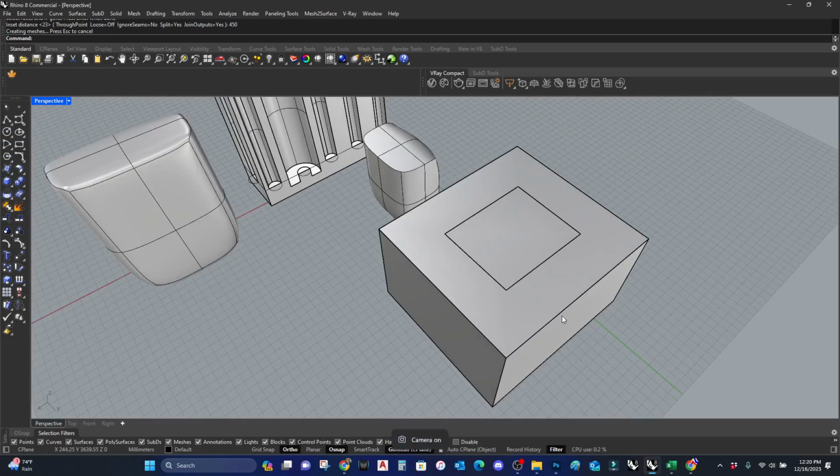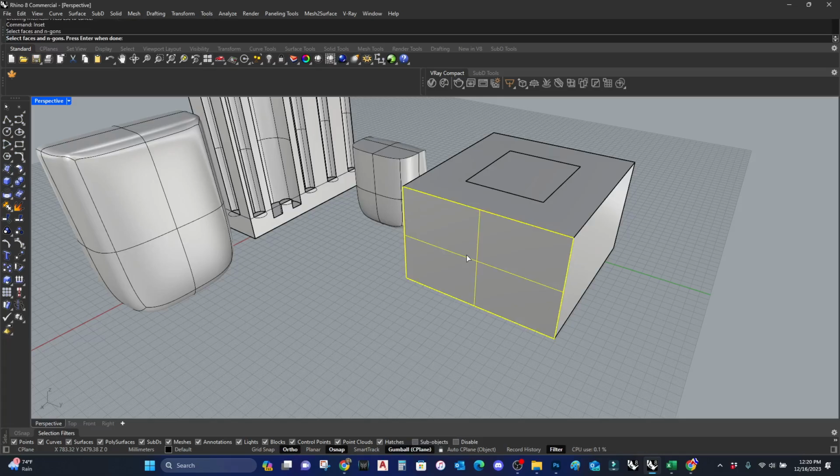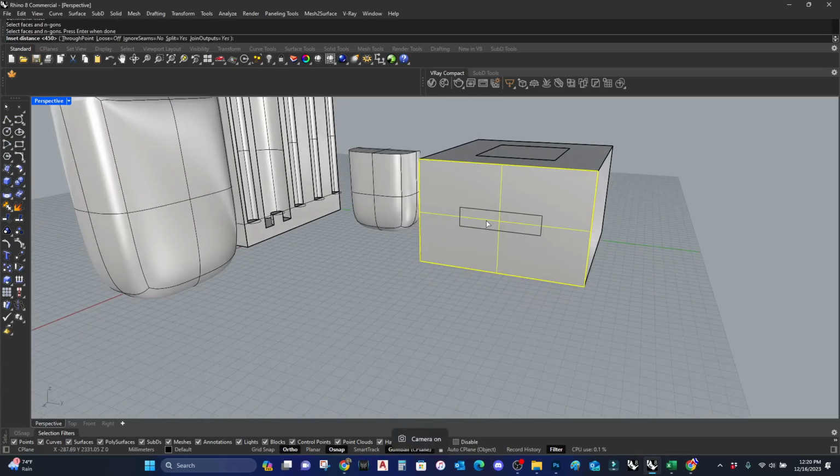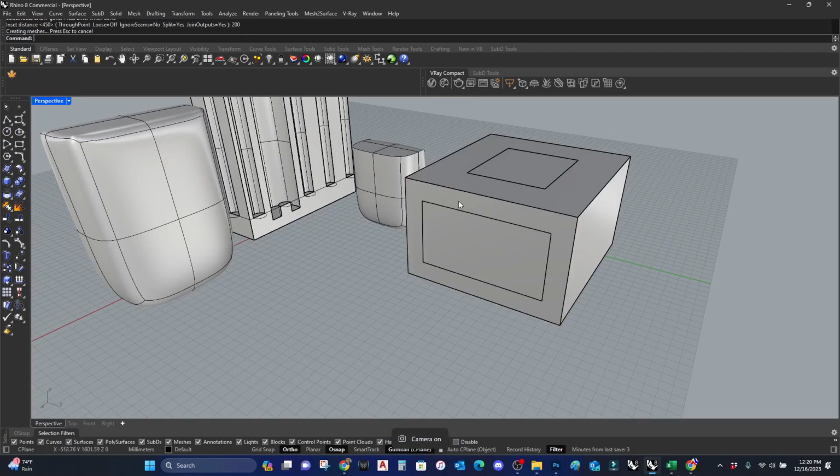By selecting a surface, it'll acknowledge the curve. So you don't have to type dupe edge and then join the layers and then do an offset curve. It just does it automatically with the surface. So if I click enter again, I can click this surface. It already acknowledges what plane it has to offset. I'm going to go 200, and that's it.